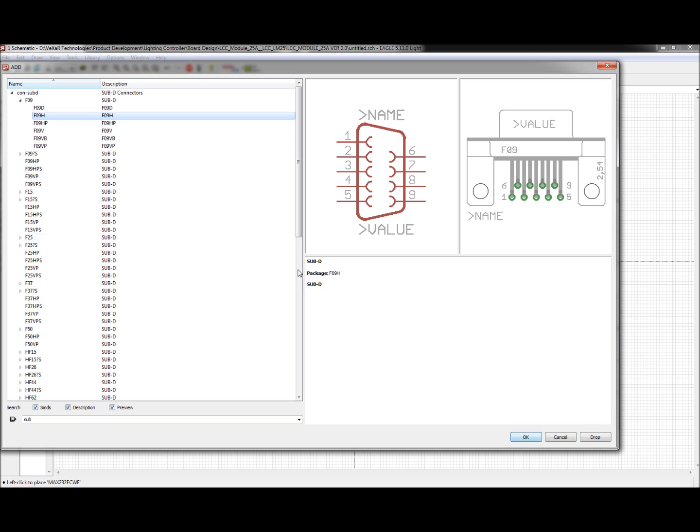That way I like the through hole one better than the surface mount, because a lot of times with surface mount stuff, unless it has some sort of through hole, if you're going to be plugging stuff into it, usually you're pushing a lot of force on the connector when you plug something into it. And with surface mount, you're just relying on the glue, basically, that's gluing the pads down to the board to take all that force.